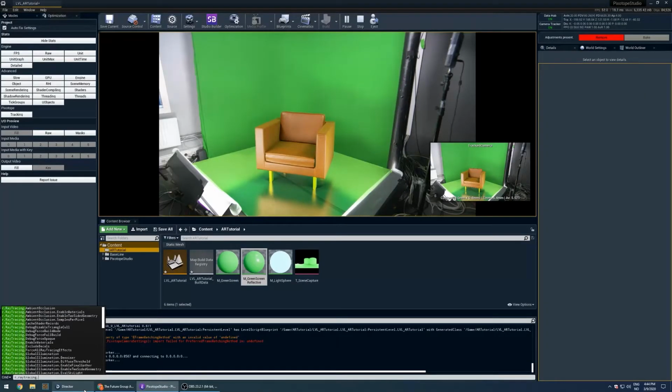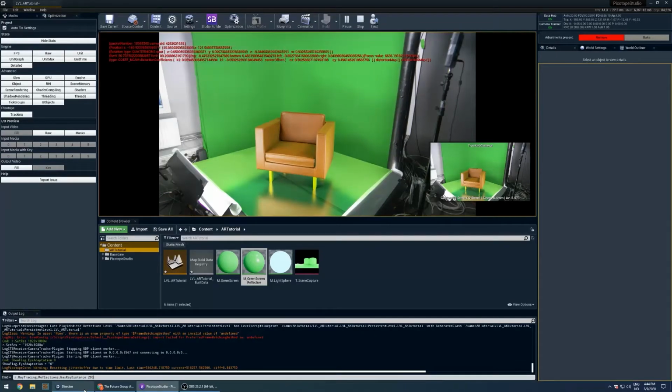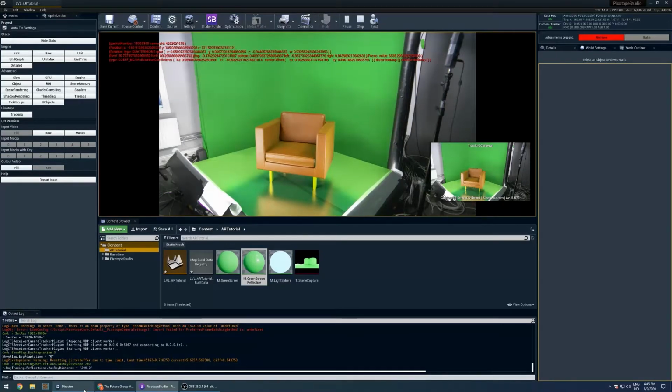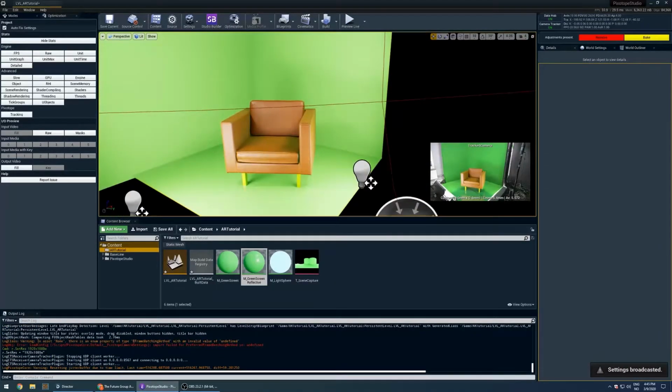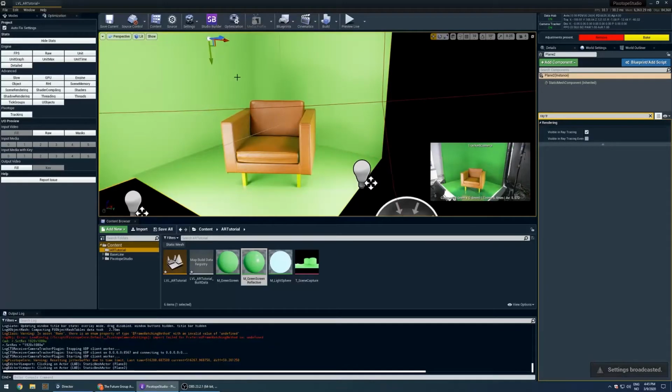And you can also see that the wall geometry is being reflected on the floor, and we don't want that. As of now, there are some ray tracing parameters that are only accessible through the command line. So I'm typing r.raytracing.reflections.max_distance, and I'm setting this to 200.